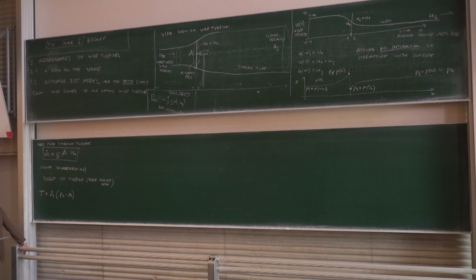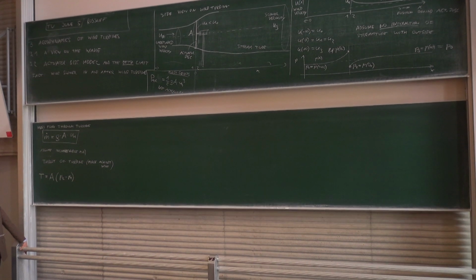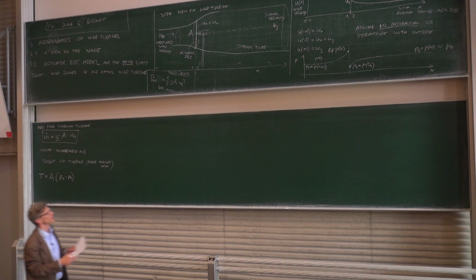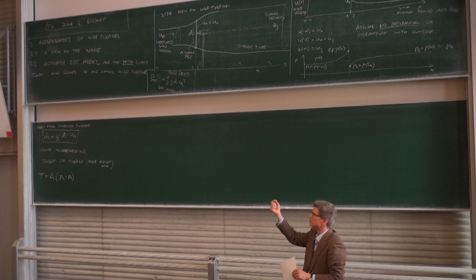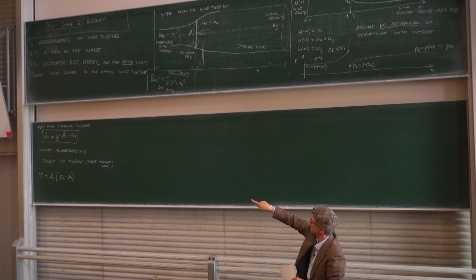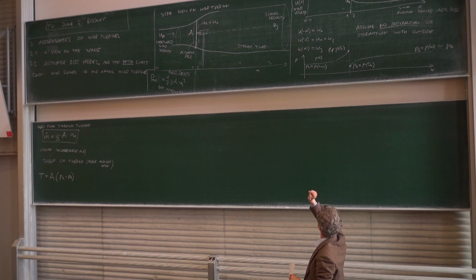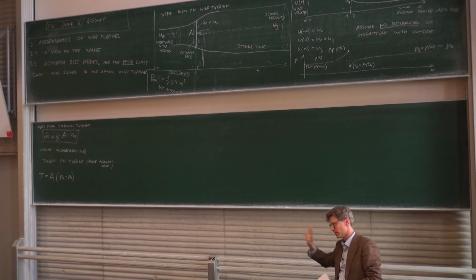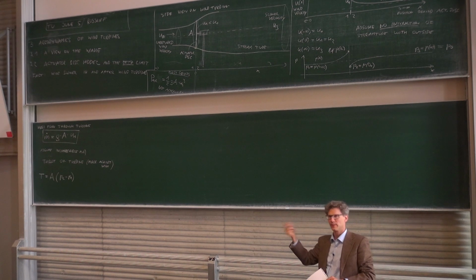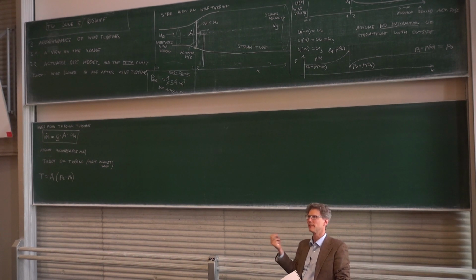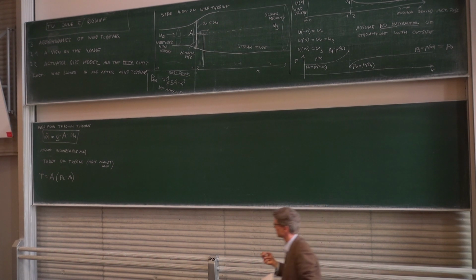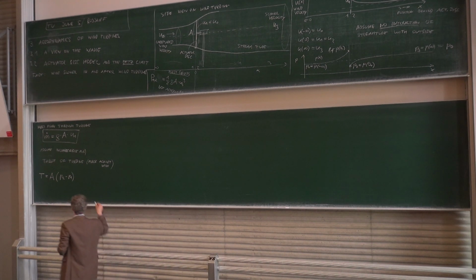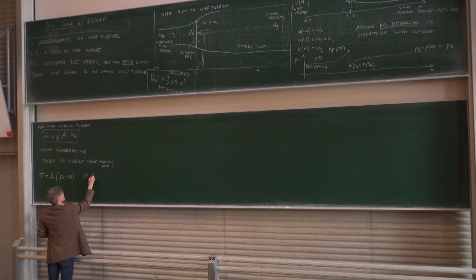But we can also have the same from another perspective, and that would be the perspective of the fluid. What does the wind turbine do? If you just look at the top, it takes air with velocity u0. All this air that flows through the turbine first had the velocity u0, and then due to this force, it will get slowed down. And slowing down of mass is exactly what we call change of momentum, right? That's what force is equal to, the change of momentum. So this would be the pressure equation. By pressure, we get this.